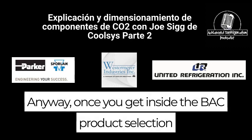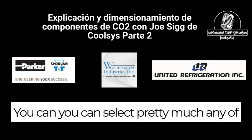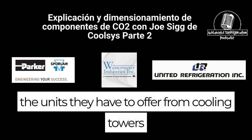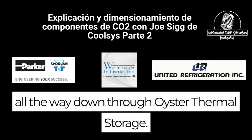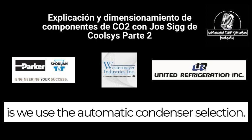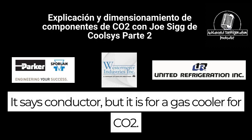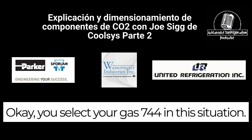Anyway, once you get inside the BAC product selection page, you just have to register for it. They'll give you an account. You can select pretty much any of the units they have to offer, from cooling towers all the way down through ice thermal storage. What we tend to use a lot is the adiabatic condenser selection. Don't let it fool you. It says condenser, but it is for a gas cooler for CO2. You select your gas, 744 in this situation.